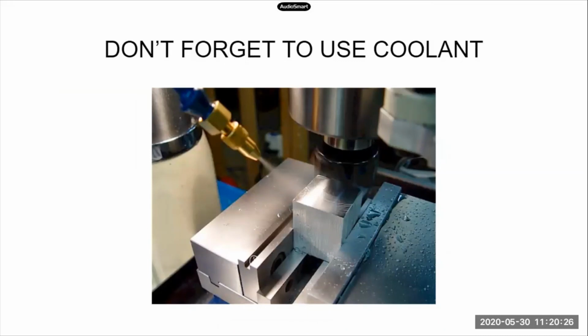Do not forget that coolant is an important part of this. These things are spinning really fast. The tools get really hot. It does help a little bit with the way that it's interacting with the surface. But the biggest thing that comes to mind for me is if you have this tool going super, super fast against this metal, it'll get pretty hot, especially if it's a harder to cut metal. So it's important to remember that you're going to need to cool that part. Otherwise, the chips may stick to the end of the tool. It may mess with some other stuff. It's just not a good time. So you want to keep in mind how these things are going to work.